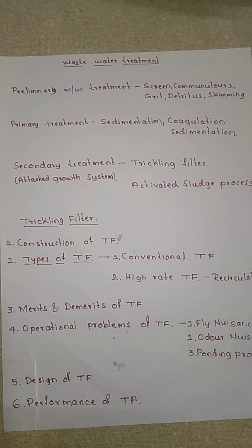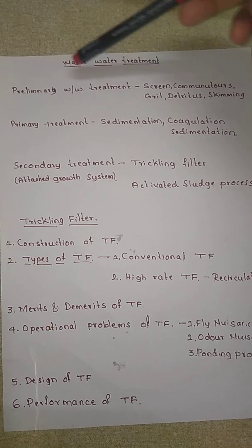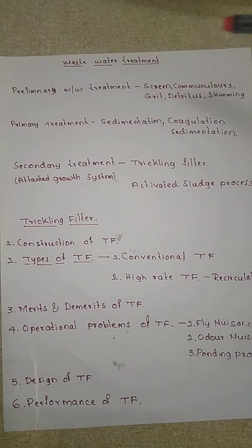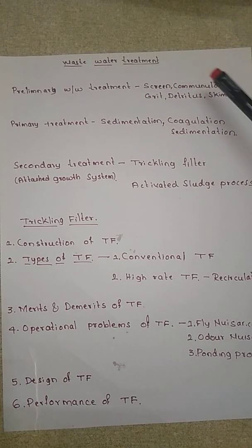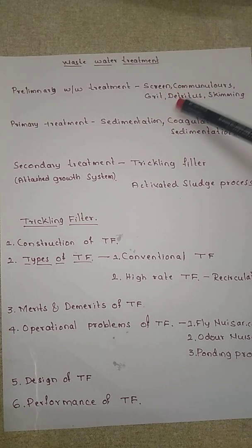In the previous classes, we have covered the preliminary wastewater treatment. In the preliminary wastewater treatment, we have already discussed screening, comminutors, then grit chambers, detritus tank, skimming tank. In the primary sedimentation, we have discussed in detail regarding sedimentation and coagulation sedimentation.